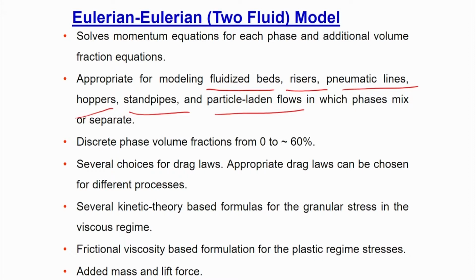You can use this model for almost all cases, and that is why the acceptability of this model is also relatively higher, because we are solving the individual phase equations and coupling those phases with the drag and other forces required to handle the higher order coupling. We will discuss the equations, but that is the way this whole thing works, and it has been used for modeling all kinds of reactors.